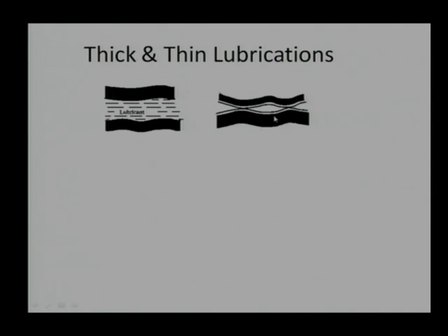So, this kind of lubrication mechanism is very sensitive towards the operating condition: increase in temperature, increase in pressure, or hard asperities coming into contact will disturb the lubrication mechanism. So, as far as possible we should avoid it and come to this solution. This is a much more robust system.